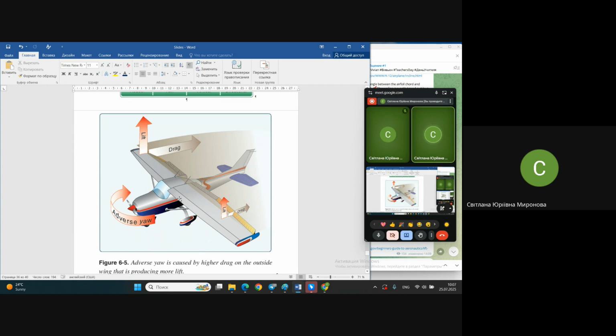I'm not satisfied with this three-dimensional picture. You will understand later with what, but anyway, I'm grateful for this picture. It helps us to understand something, to imagine. Look, in one half of the wing, the aileron moved down. In the other, closer to us at the left half wing, it's moved up. What did it result in? As we spoiled the curvature of the airfoil here, we have less lift here. Here we have more lift. Here we have less lift. What happened? The left wing, it falls down right now. Agree?